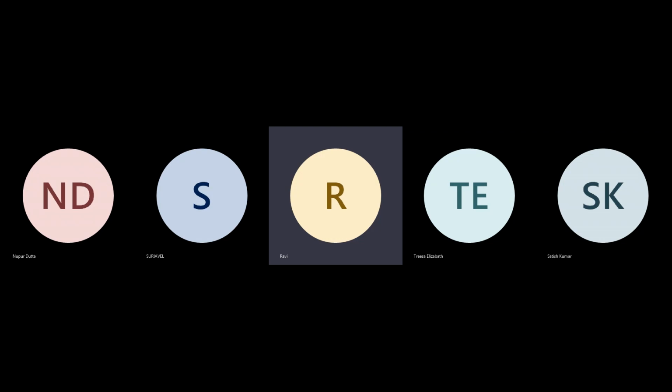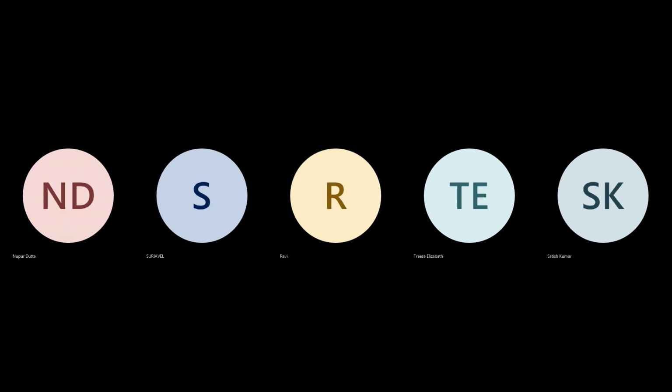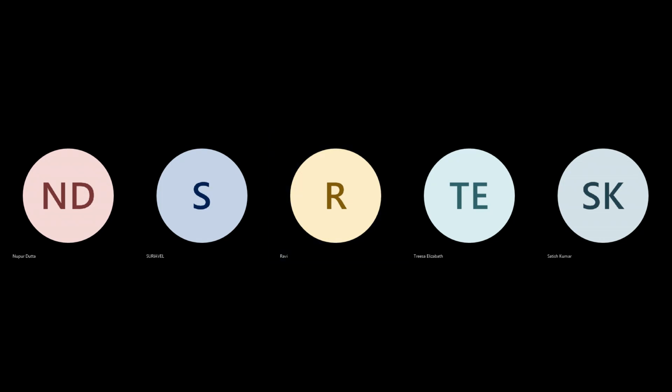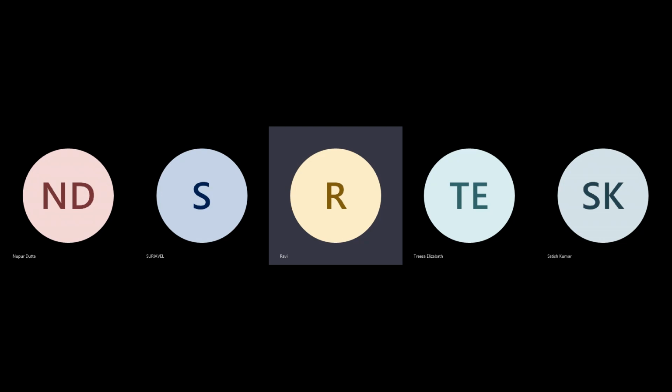This is also a script that you will have to create for your own needs. Don't assume what the tool has given. You will have to create your convergence flow. That is what placement is: you have to create a convergence flow that will enable you to converge your timing. They will give you a set of commands, a base flow, but if you have to converge, you may say, I'm getting this, can I do one more piece of optimization, then one more iteration? Then you'll have to experiment with options, with additional runs, whatever is required.